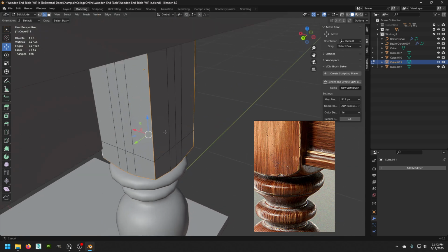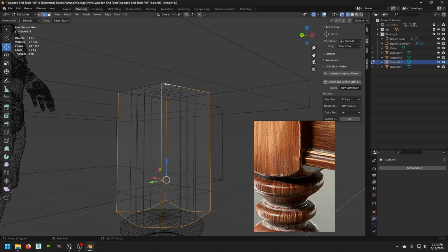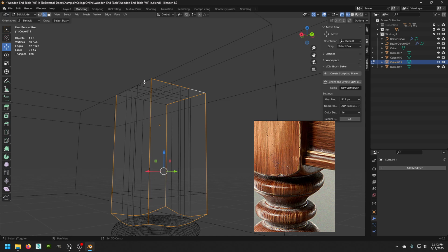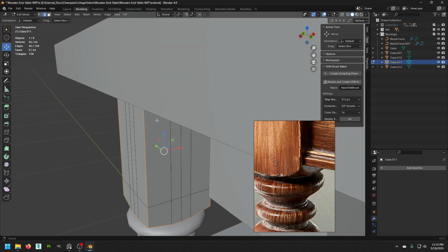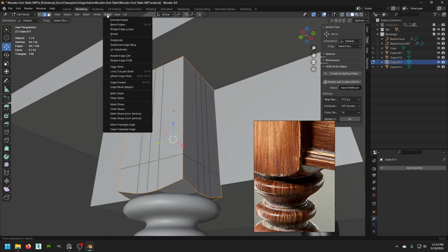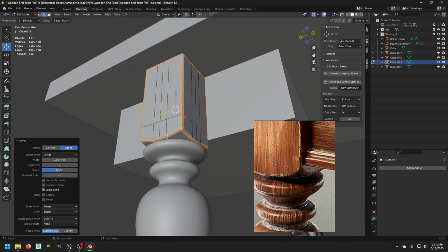Better on the silhouette. Now, just to make sure, we're also going to hit these top ones as well, because I kind of like to have the entirety of the asset to kind of be similar. And then we'll use that bevel again. So go ahead and add that back on. Okay, have it nice and chunky.